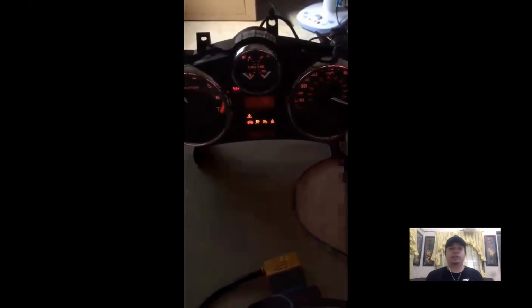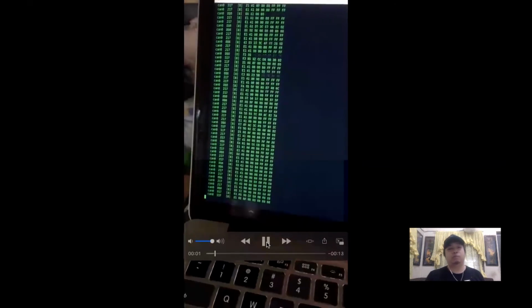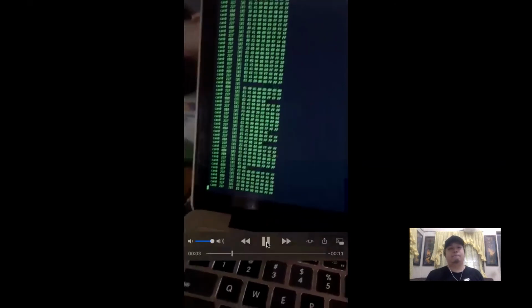I'm trying to fuzz the instrument cluster of a Peugeot 207. So that's it. With just a cluster for $20, you could already try this and have your NanoCAN fuzz and play with your instrument cluster. So you don't need to have an actual car yet. You just need a couple of components to start playing with CAN. Basically, that's it.